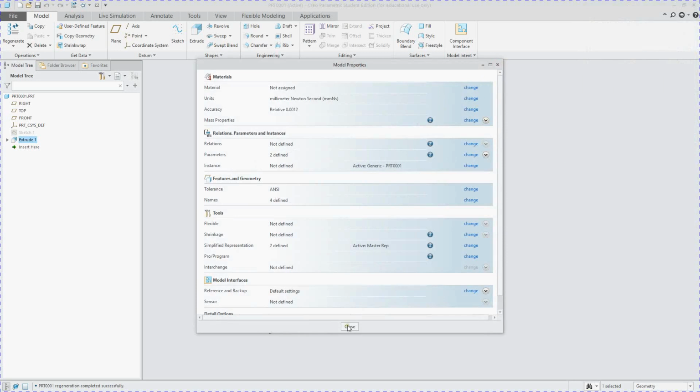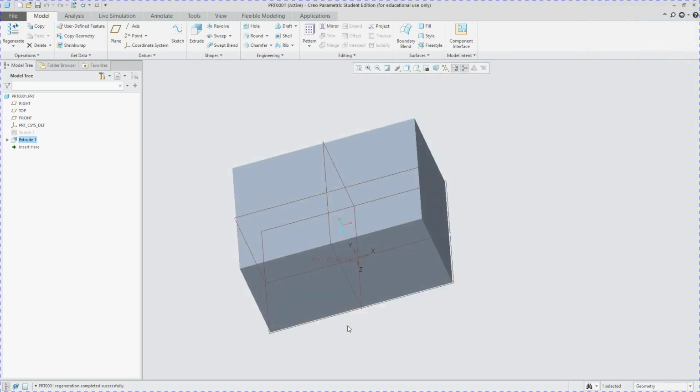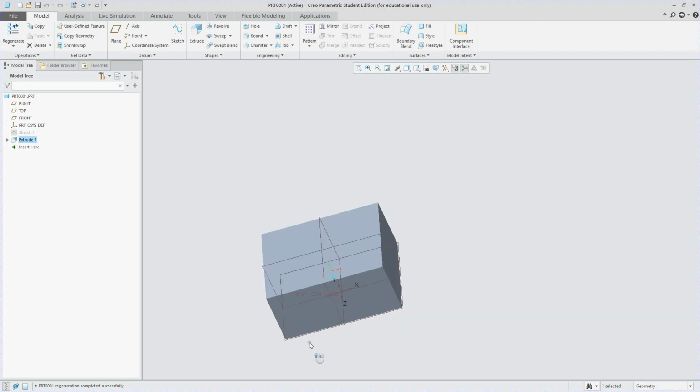Simple. And you can do that at any point. So if you go through, do all your design, realize that you did this for some of your pieces and they're in millimeters, then you closed CREO, reopened it, and it went back to inches. You can then change this after you've entered all your dimensions, created all your objects, and it will change the size of the part accordingly. So don't worry if you forget about it, you can do that part at the end.